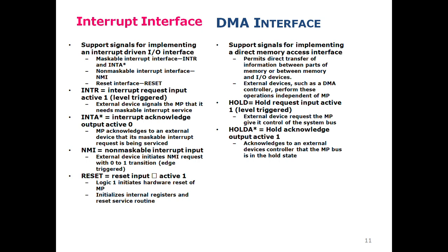But still this operation needs to get access to the master bus, or the system bus, and this request is sent to the microprocessor through the HOLD pin. Hold request input, active high, is level triggered. The external device or the DMA controller requests the microprocessor to give it control of the system bus,